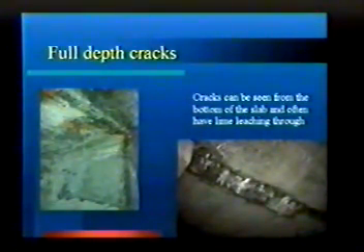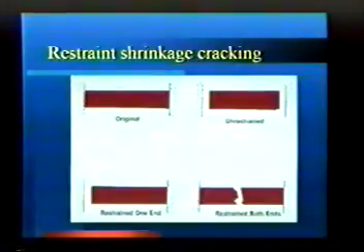Okay? Of course, full depth cracks. This is a little bit larger of that previous slide where I have the 4-foot long stalactite. And then you can see on this one, you've got the lime leaching out of the concrete. I mean, that is lime that comes out of the concrete. And if it hits a car inside of a garage, it's a written guarantee it's going to take the finish off of a car. So you need to solve that problem.